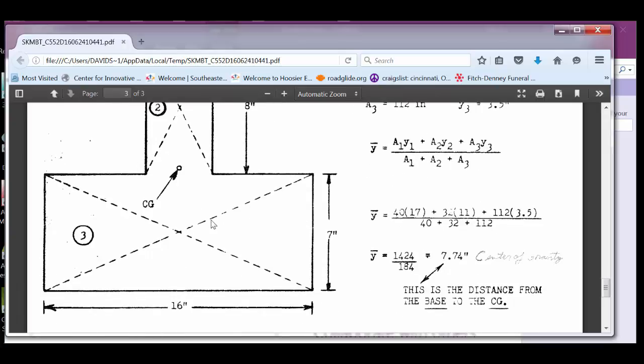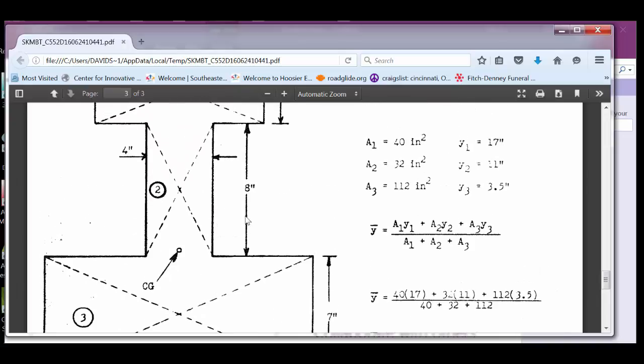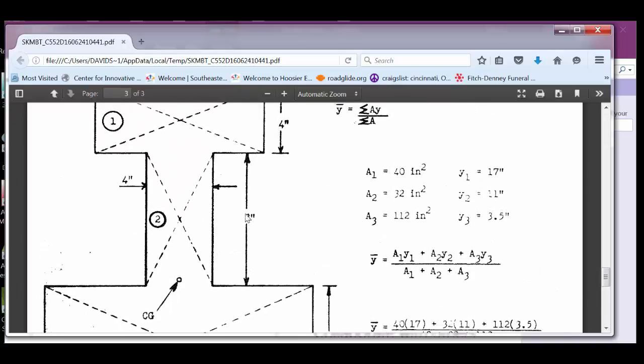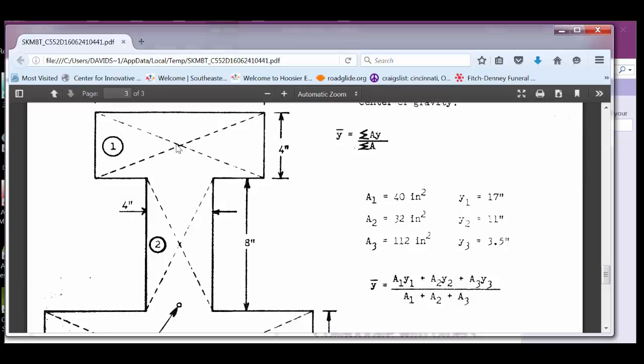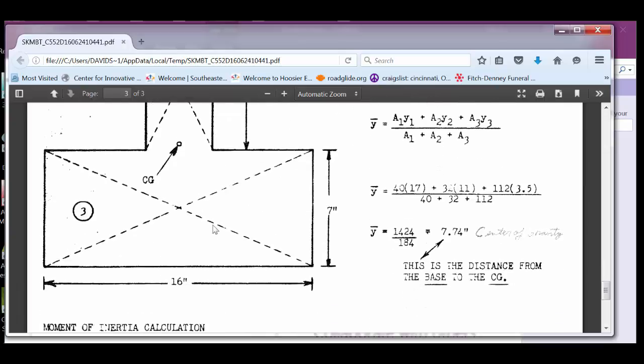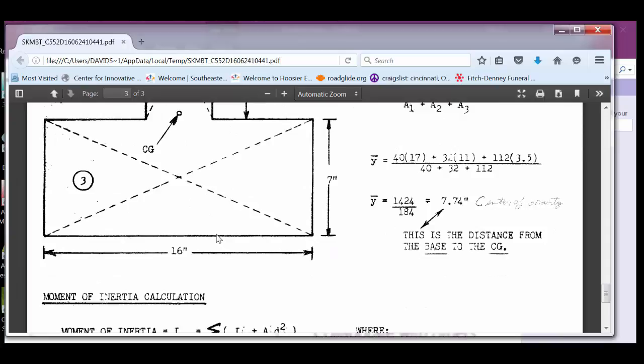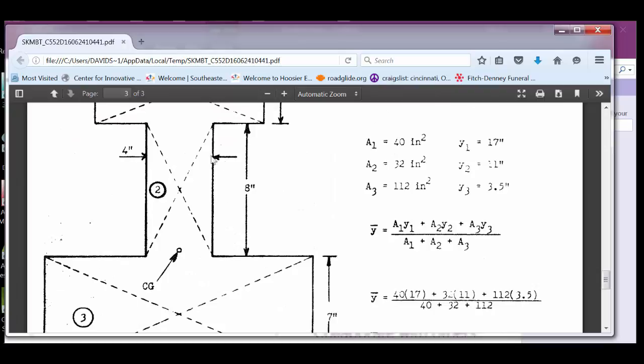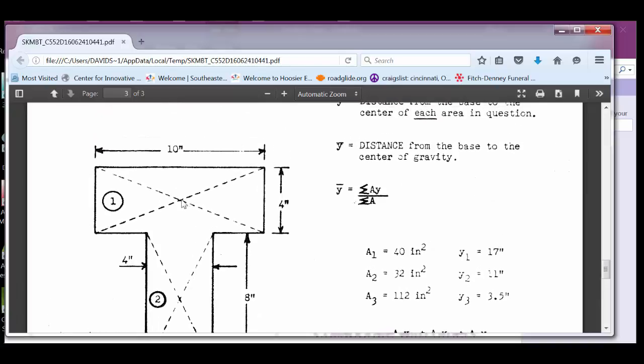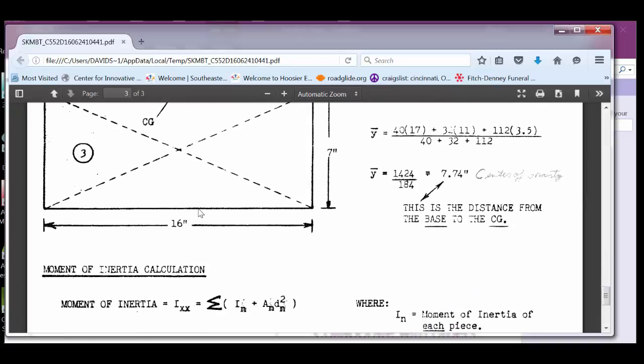Why are you doing the total on 2 of them and then halfway on the third? I'm not following. You're finding where the center of gravity for this particular block is relative to the y-axis. Okay, and you know that your y-axis is... Right. It's just like you could ignore the fact that this block and this block are here. What would the center of gravity be for this piece if it were suspended that far from that axis? So the bottom of the piece.